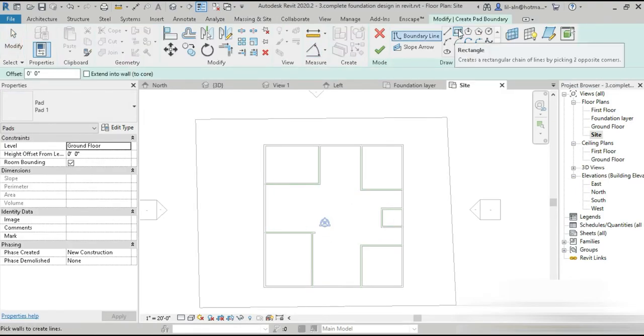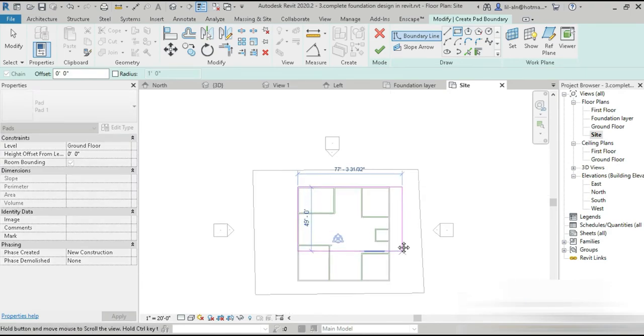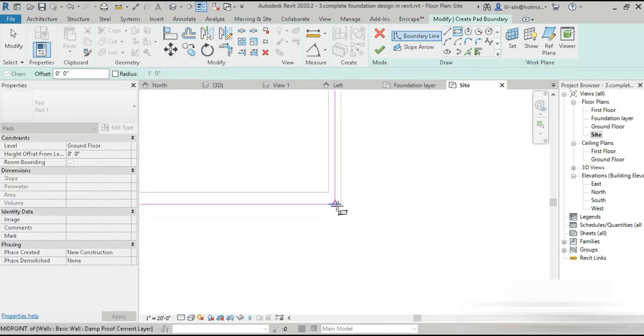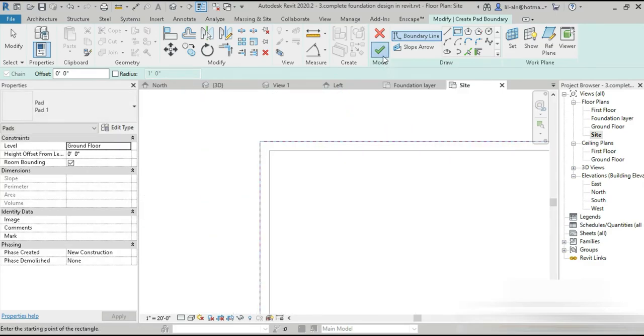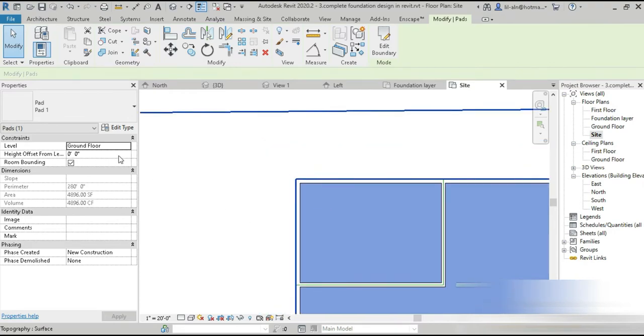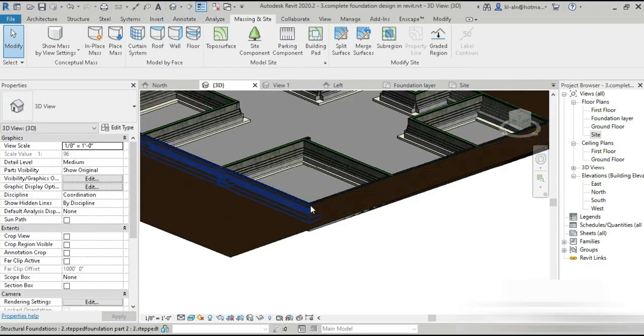Whenever you want to make a sort of a trench, you always place the building pad. So the building pad can be from here to right here. And our boundaries, right? Yes, they are right. Now the building pad has to be sand filling, but height from the offset has to be minus 150 mm. So okay, now let's go to 3D view.